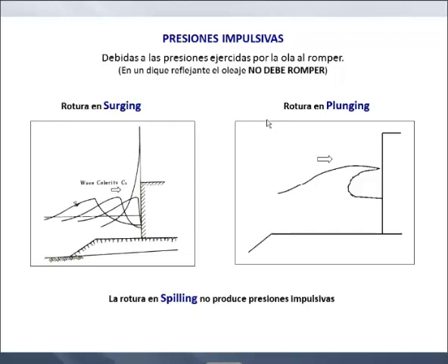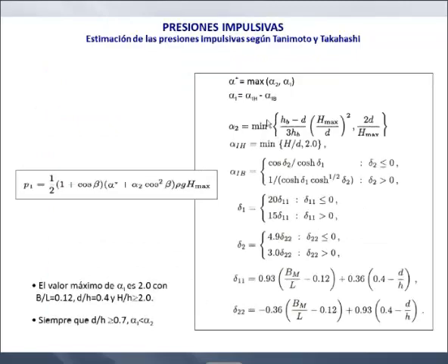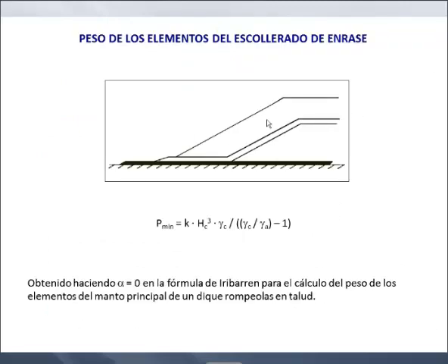One thing: you may have enormous punctual pressure, but there are dikes that are calculated taking into account these high peaks of pressure, but not considering that this is a pressure at one point. They extend that pressure to the whole of the perimeter, and they come up with enormous structures with enormous costs that make the commercial operation behind those walls not viable. That is where the money has to be made. That's a very important thing to take into consideration.